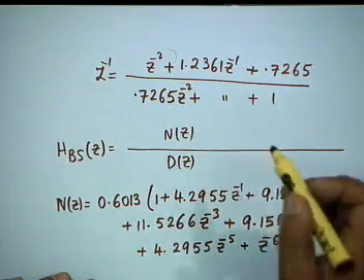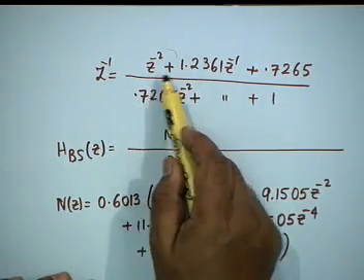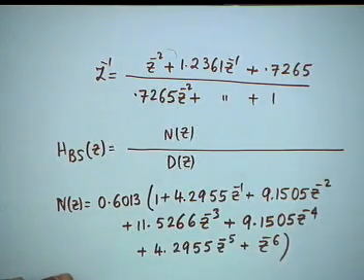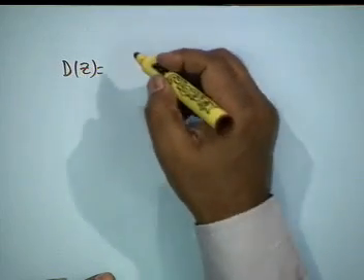All pass property gave rise to 1 minus z inverse, in the denominator of high pass, 1 minus z to the minus 2 whole squared in the numerator of band pass, and it gives a linear phase here. Linear phase is a reflection of the interchange or the reversal of the coefficients in the all pass. Okay. These are points one would like to observe carefully.